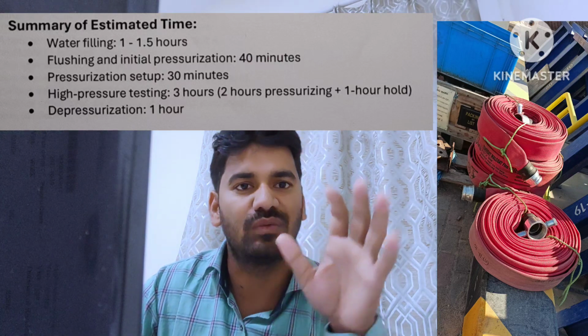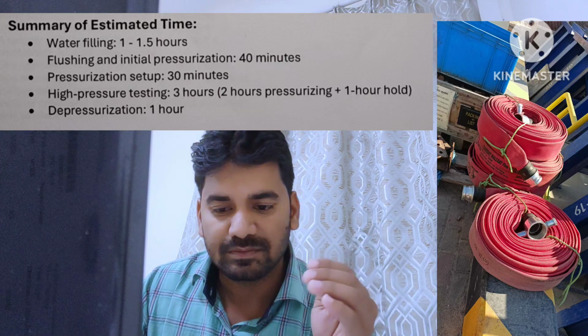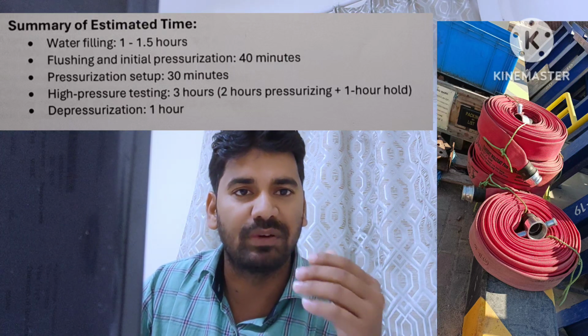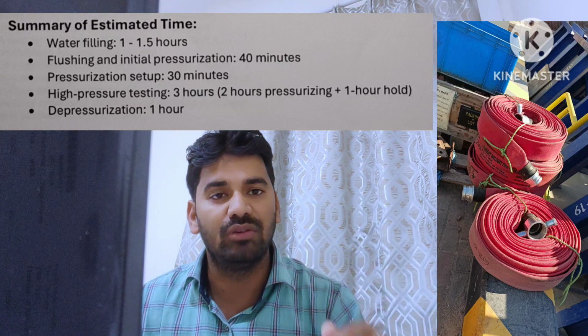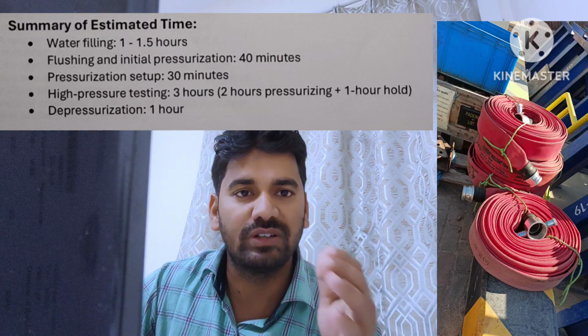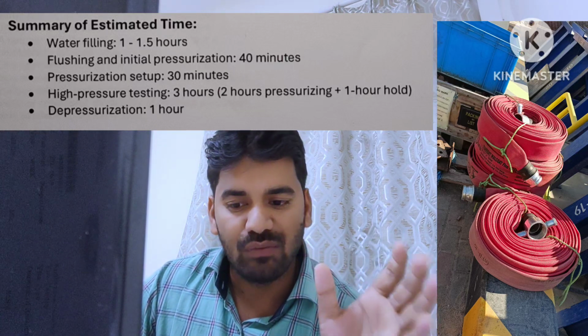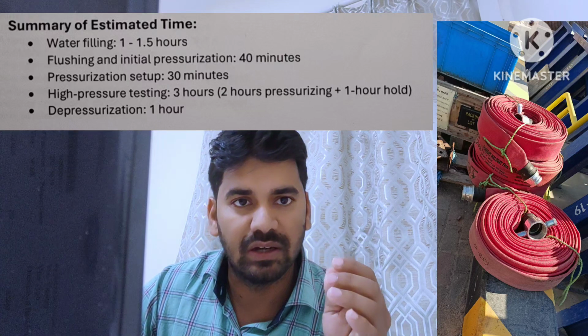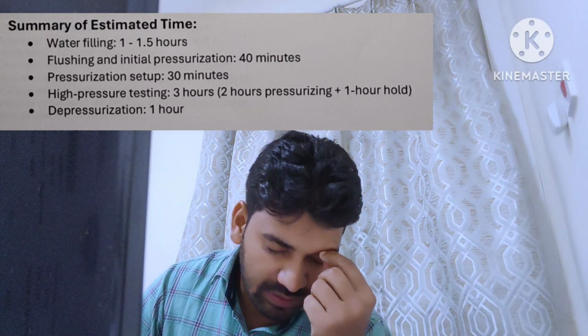So the estimated time is 1 to 1.5 hours for the filling purpose, because the fire hydrant valve is not opened 100%, so the capacity is automatically reduced. If you fully open it, it gives 60,000 liters per hour. The estimate is 1 hour for filling, but it is not opened fully. When I did the same work last year, the valve was not fully open and it took much more time.